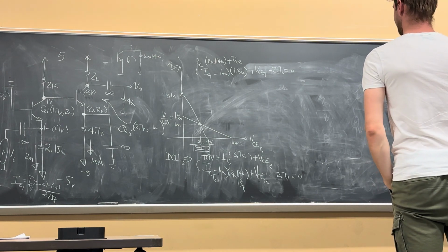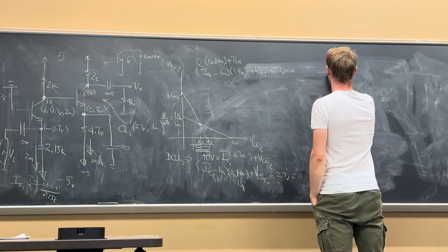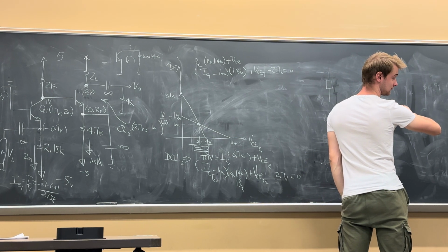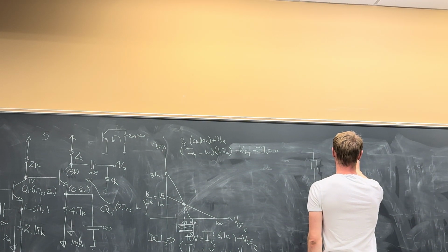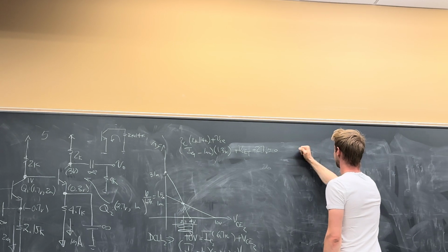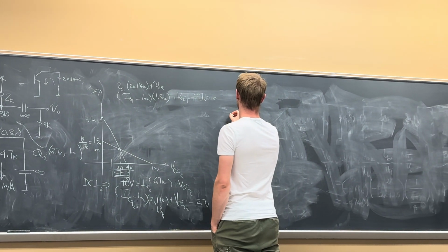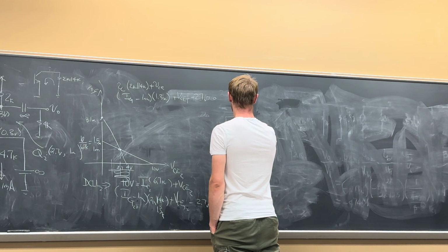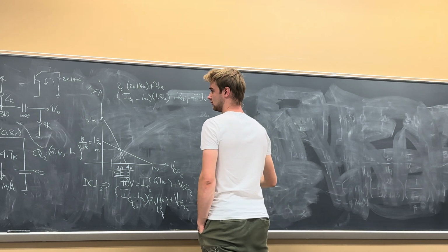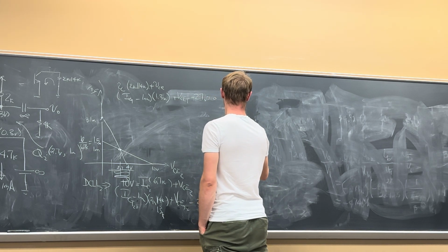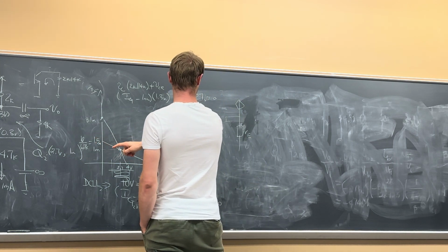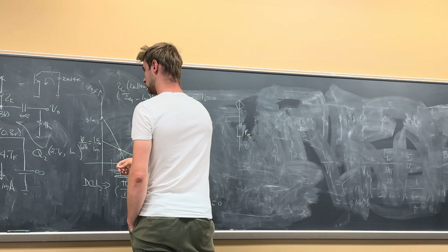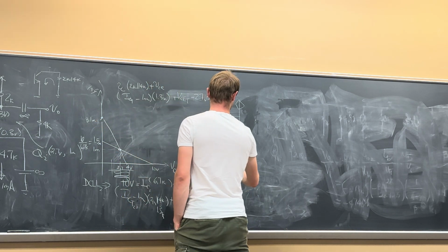Look, this is common base in the front. You can do it with the pi model, you can do it with the T model. Common base is very good to do with the T model. So what are we doing? T model. Put the T model in the front and pi model in the second. It's much easier. It's not big E, little re, that's from notation. Now the emitter is tied to Vin and 2.15K, right?